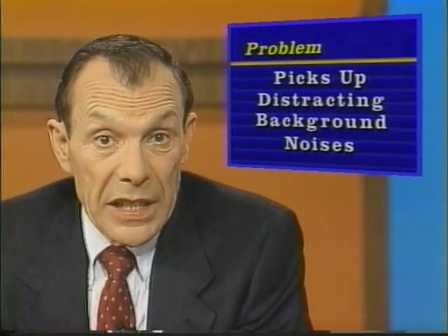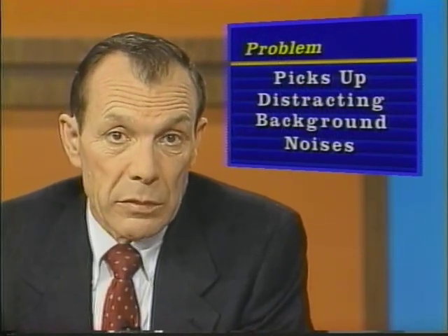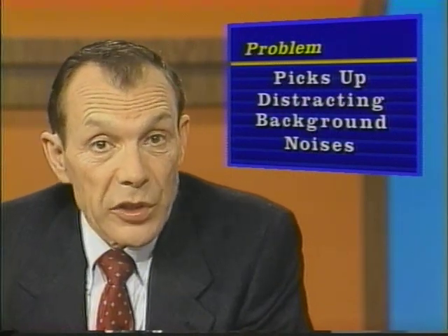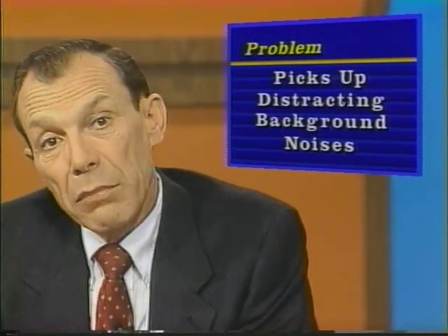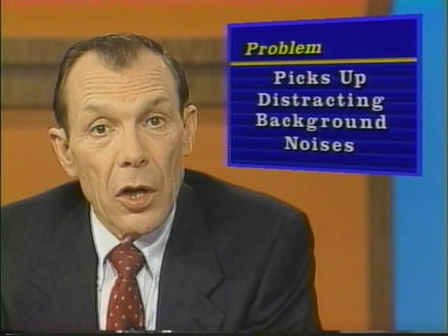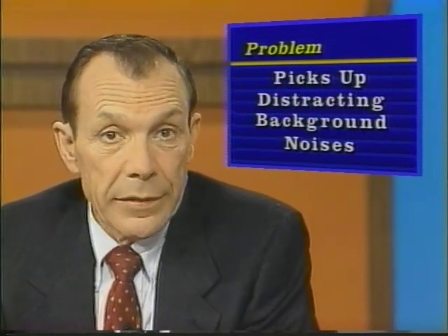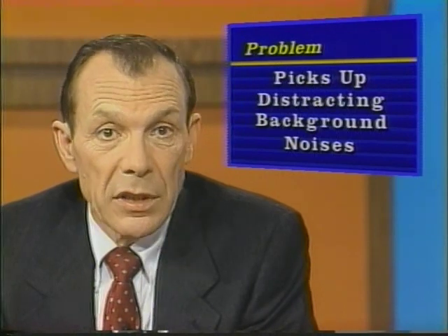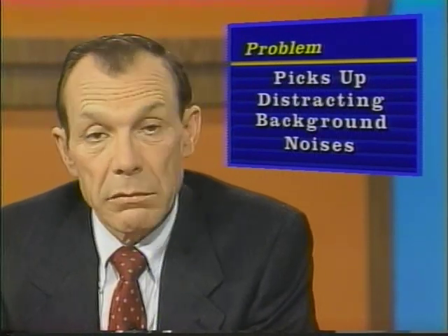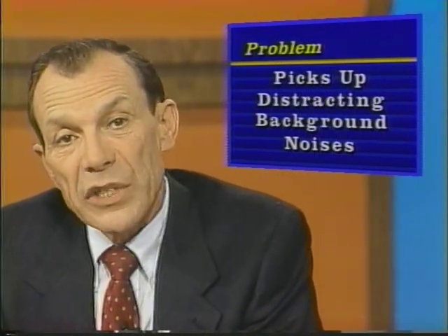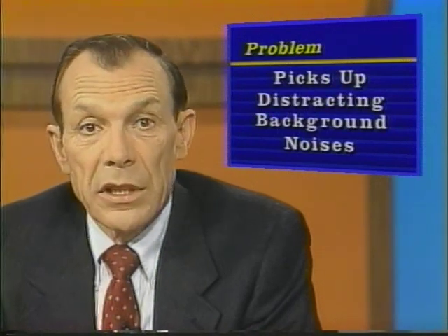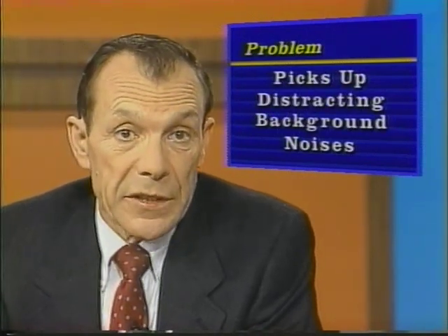Background noise is probably the biggest problem with this type of microphone. The next time you use a ground contact microphone, place it on a hard surface and listen to all the background noises you can hear: dogs barking, cars, birds, and people talking or walking around. Lift the microphone several inches off the ground and you will lose all this background noise.